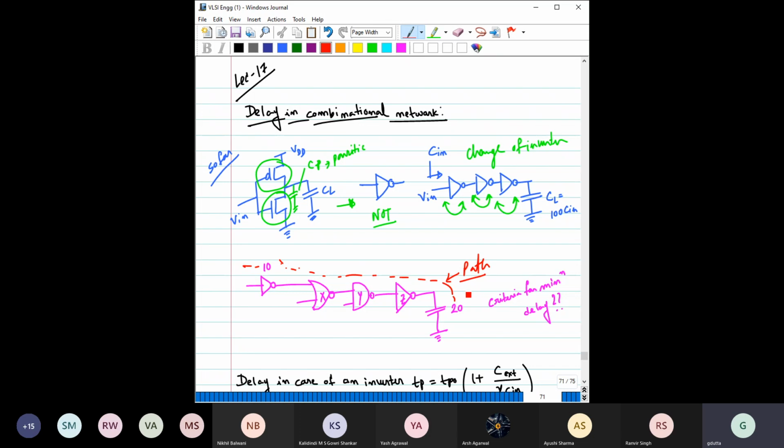If this gate is size 10, meaning 10 units of capacitance, where the unit C is always referred to the smallest transistor dimension, for the NMOS, and it has to drive a capacitor of 20 C, how do we size it?